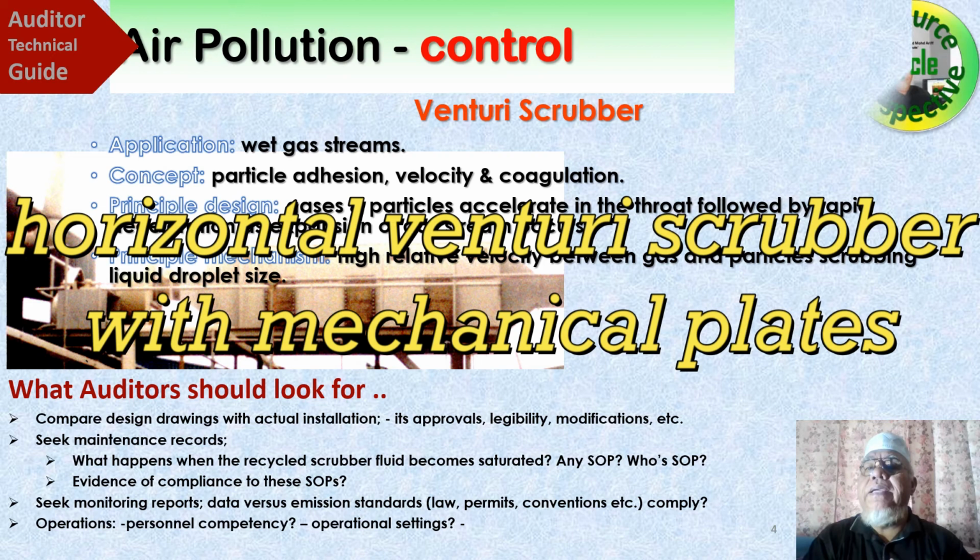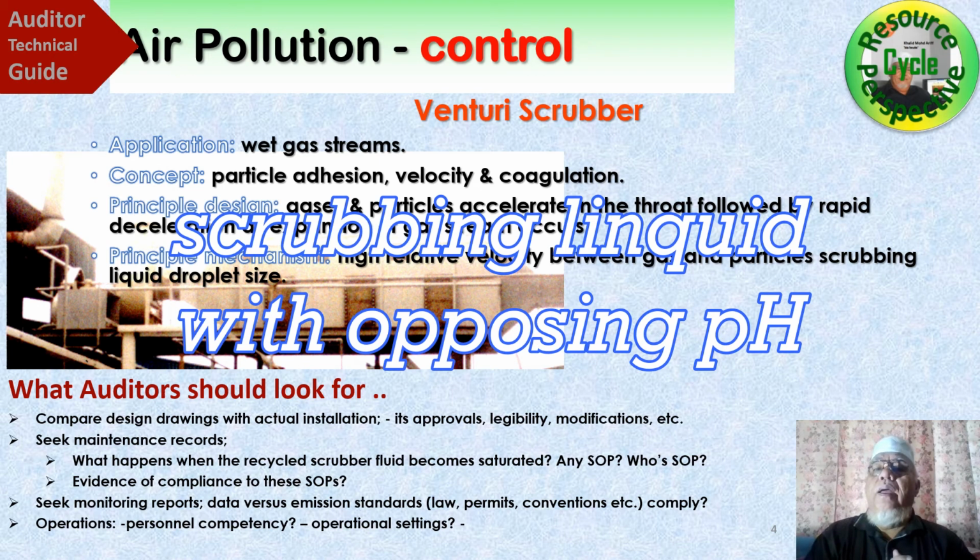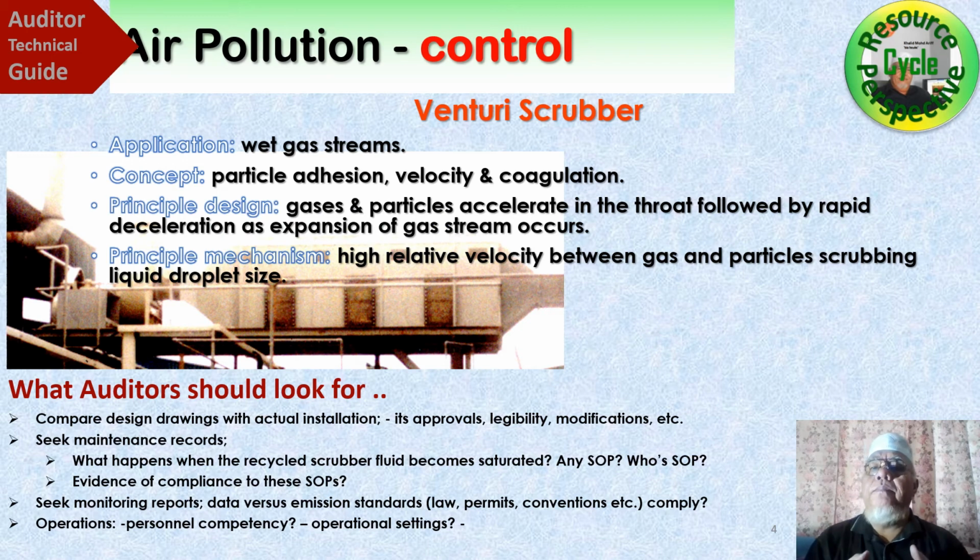As you can see, the scrubbing agent is sodium hydroxide diluted to certain molarity, and the scrubbing technique involves scrubbing liquid in a bath, then pumped to the top and sprayed down as mist. The acidic gas stream which flows in collides with the scrubbing agent and forms liquid which is collected at the lower part of the scrubber itself. Yes, the contaminated scrubber liquid is being pumped from this basin and reused or recycled as explained earlier. So it is identical in terms of operating principles, but in a different plane.